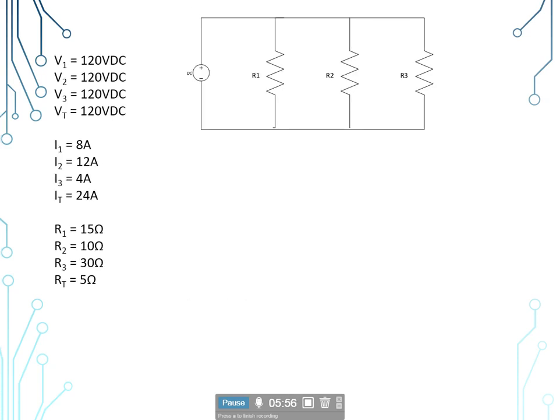And then finally we go to our total power, the wattage for the entire circuit, and the power dissipated by each individual branch. And so P sub t is equal to I sub t times V sub t. So P sub t is equal to 24 amps times 120 volts, which gives us 2,880. In electricity, we speak metric notation, so we would call that 2.88 kilowatts.